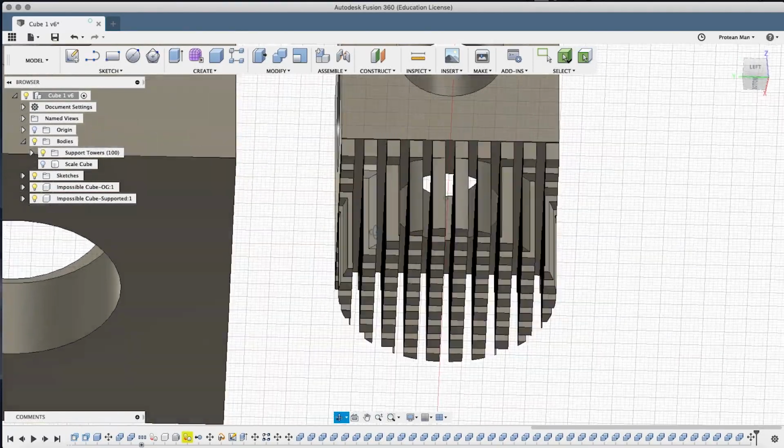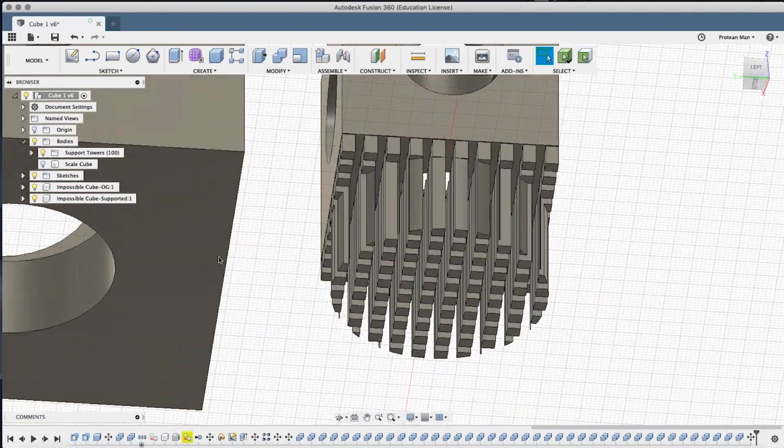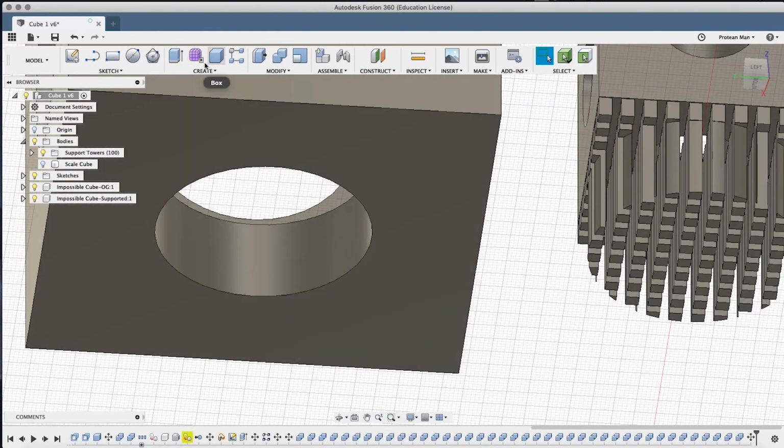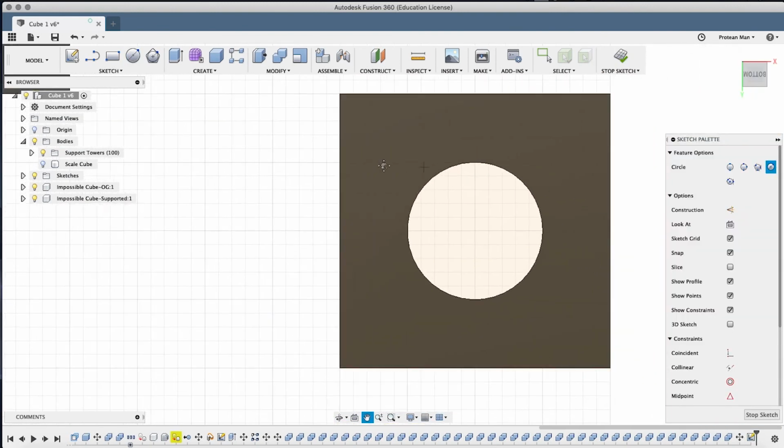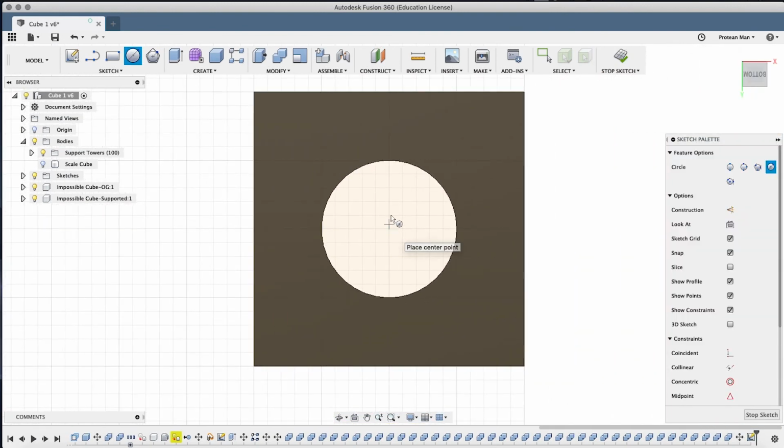You are going to create a center diameter circle. You're going to click the bottom of the large cube. You're going to find the center. Now this is where it will default, it will snap to the middle. A circle will appear. If you see a square, it's not the center.